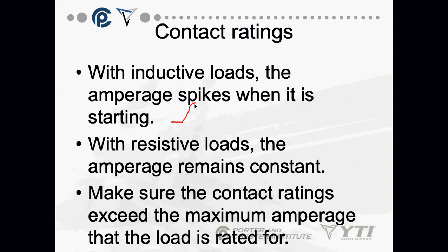As soon as the coil starts generating its own resistance, the amperage will come down and level off to the running amps. Any device that's controlling the motor has to be able to handle this spike. Once we're back down to our running amperage, there's really no issue.